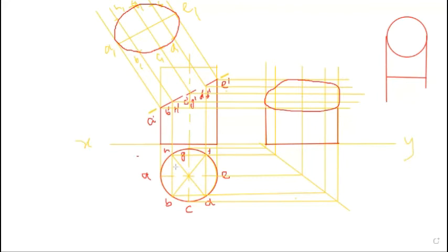So here, axis AE, this must be 45 degrees in this way, and the gap between two will be 1 to 2 millimeter, not much more. This is the hatching line, meaning your material is removed from the solid body. Here material removed. Similarly here also. Here you see the 45 degree. If you draw the vertical line, this will be 45 degrees with the axis.